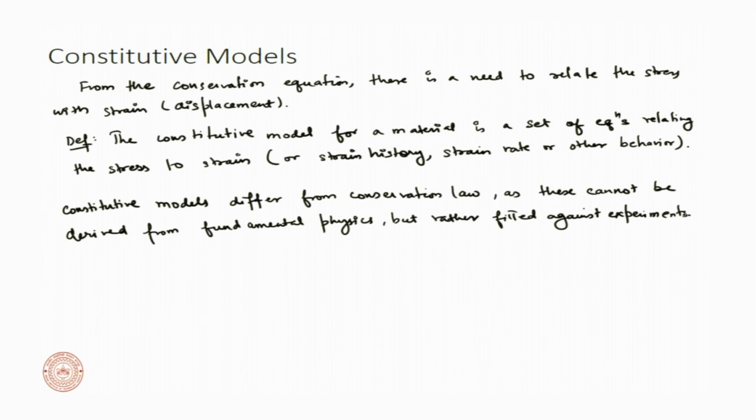Okay. So, these expressions or these constitutive models, unlike the conservation equation in which we saw how Newton's second law was used to develop that expression, cannot be determined by fundamental physics. However, these can be determined by fitting against experiments. There are some fundamental physics that is valid, based upon the plane of symmetry or the crystal symmetry. We will come into those. But those are the material behavior, and how we understand the material behavior is based upon experiments.